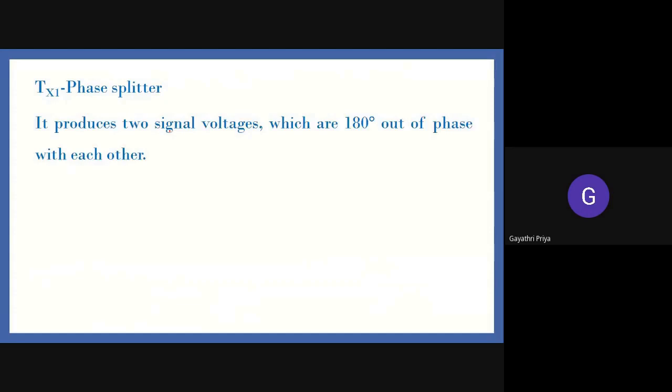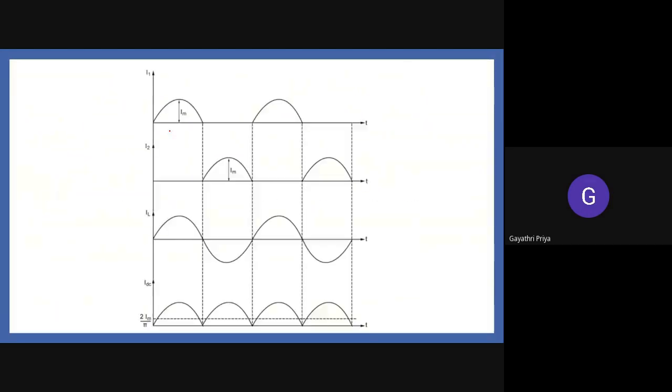Let us see the working of the transistor. Initially, the transistors Q1 and Q2 will be selected or biased in such a way that both of them remain in the cutoff region. How could that happen? At both bases we provide a bias voltage less than 0.7 volts, that is, less than your cut-in voltage. The bias is present at the base terminal. Therefore, the same thing we have explained here.